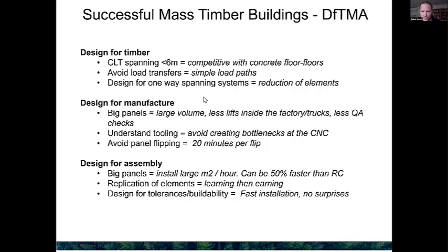And finally, which is a bit close to what we're talking about today, is designing for tolerances and buildability. I mean, you don't want the panels to get to site and then things aren't fitting, and you might have some precast elements or some cast-ins, and then all of a sudden you're post-fixing everything and there are a lot of surprises on site. So this is what we want to be avoiding as much as possible.